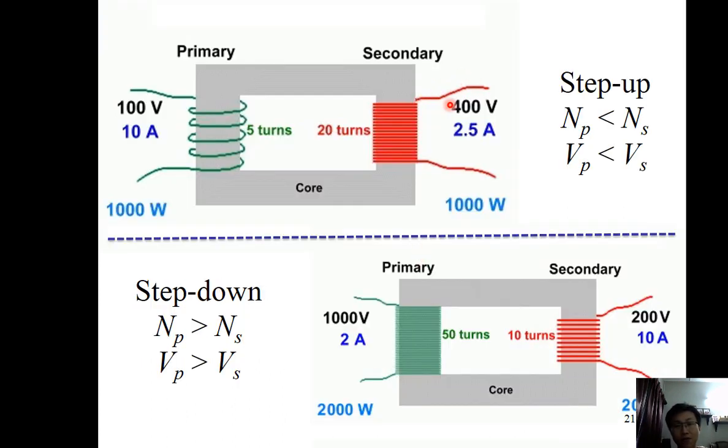So the EMF generated here will be AC as well, because it is varying. AC current injected in the primary winding will create clockwise and counterclockwise magnetic flux. The clockwise and counterclockwise magnetic flux cutting the secondary windings will generate a varying EMF. We call it an AC EMF.